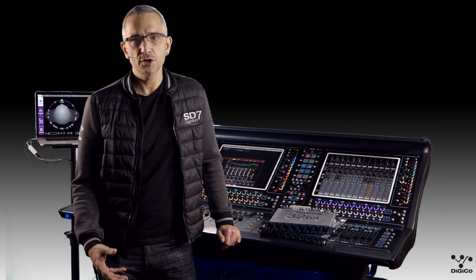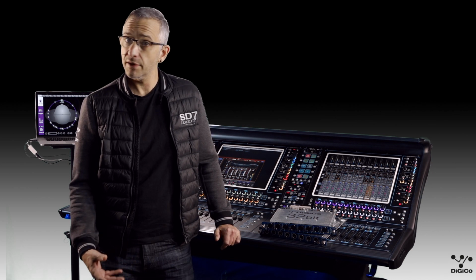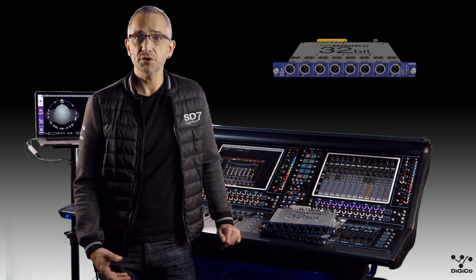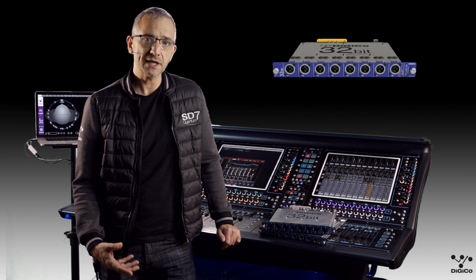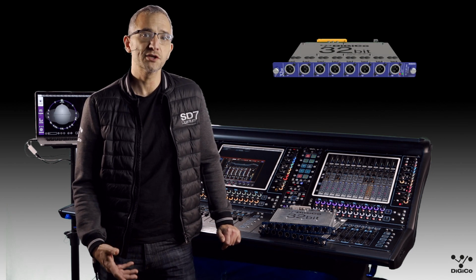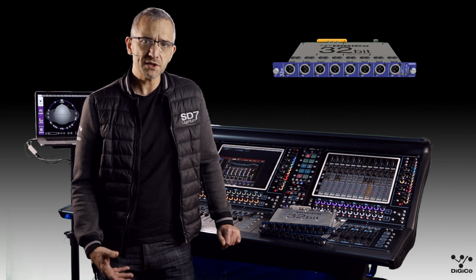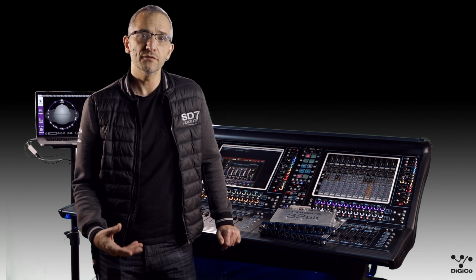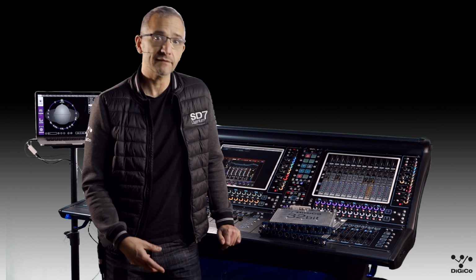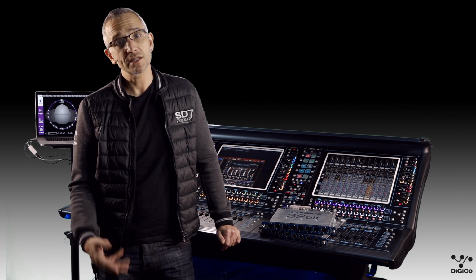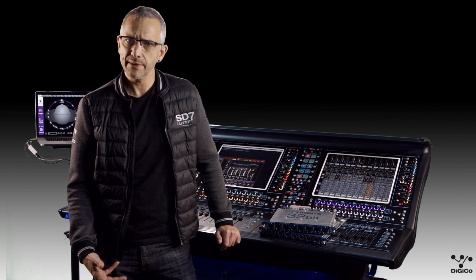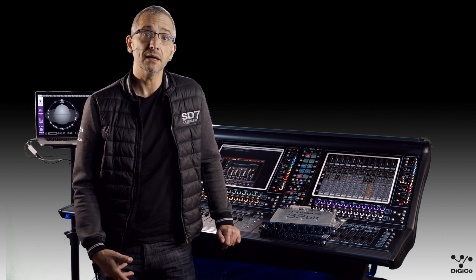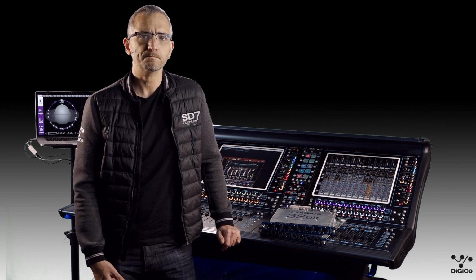Having launched the 32-bit preamp card, we set about making a 32-bit output card. Using the same technology and all the tricks and knowledge from designing the input card, we put together our ultimate Stadius 32-bit DAC. And the performance of our 32-bit DAC is equally amazing. A THD plus noise figure of 0.0008% from 20 Hz to 20 kHz, minus 99 dBu noise, which is 6 dB quieter than the 24-bit card, and a dynamic range of 121 dB, which is a 6 dB increase.